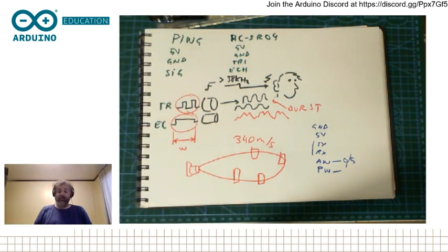It's harder to program. You need to use 2 pins instead of 1. But at the same time, if you had, for example, an array of these sensors, you could distinguish whether something is oriented in one direction or the other by having one of the sensors transmitting and all of the other ones receiving. Since you know the distance between the sensors, you could do the math to detect whether it's pointing that direction or that direction versus a wall, for example. So this is a bit more versatile. You can do more things with it.